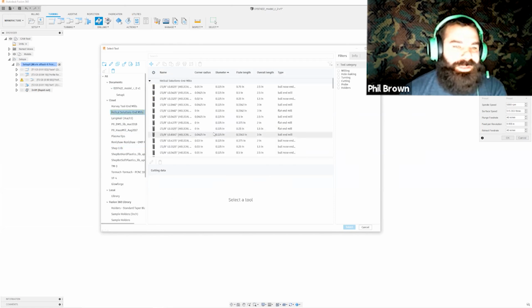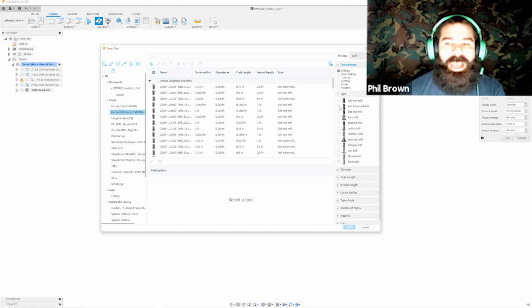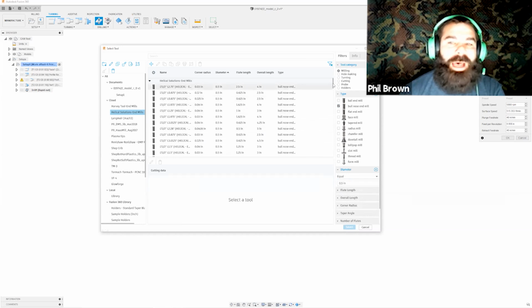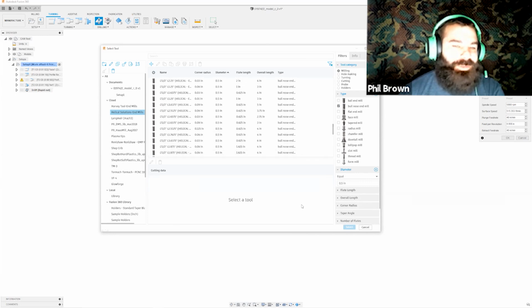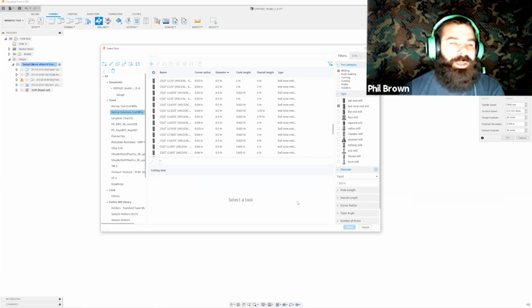The neat thing with Fusion 360, I do know that there's not a spot drill in this category, but I did show this to Greg. So I downloaded the entire Helical Solutions end mill catalog. And in the event when we get into milling, you'll see me simply come in here and say milling. I want maybe a flat end mill. And then lastly, my diameter on my end mill, I could say equals 0.5. And you're going to see as I do this how many tools populate, that's a 1/2 inch Helical end mill. So I have the entire catalog built inside of here to be able to search by their part number or to be able to find a tool that works, then look at their speeds and feeds from their tool library.